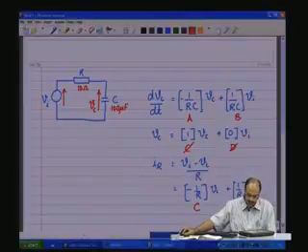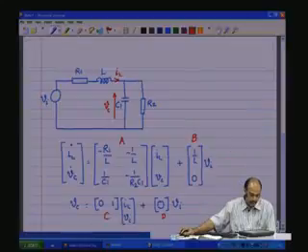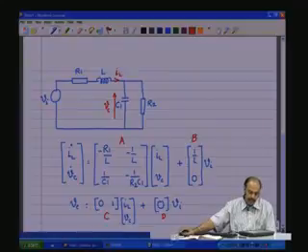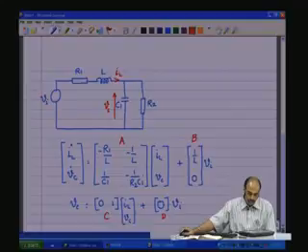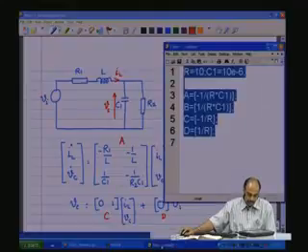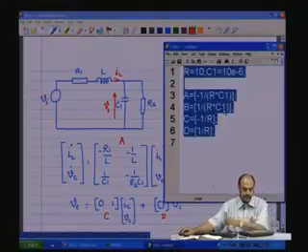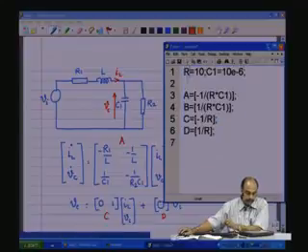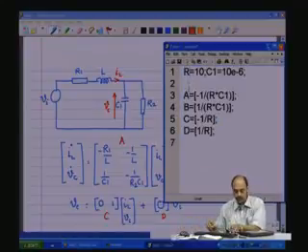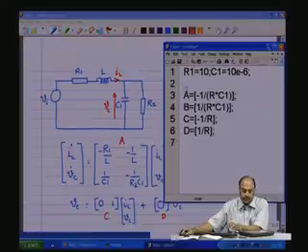Now, coming back to the circuit of interest now, which is the LC circuit. So, these are the A, B, C, D matrices that we need to input. So, let us go back to the editor here and edit these things. So, we need a parameter R1, and let us say we give R1 of around 1 ohm.